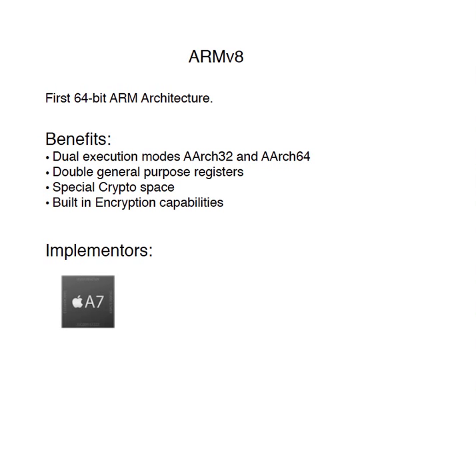It has something called dual execution modes, which means it can switch between 32-bit processing and 64-bit processing just like that. Those execution modes are called AArch32 and AArch64. Taking an example, iPhone 5s has a 64-bit processor, but all the apps which are built for 32-bit processing still run on the iPhone 5s. That is the key point of dual execution modes.